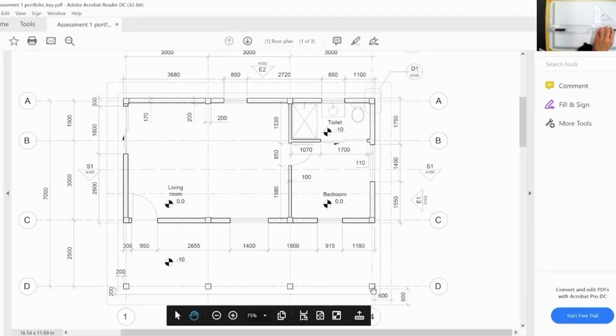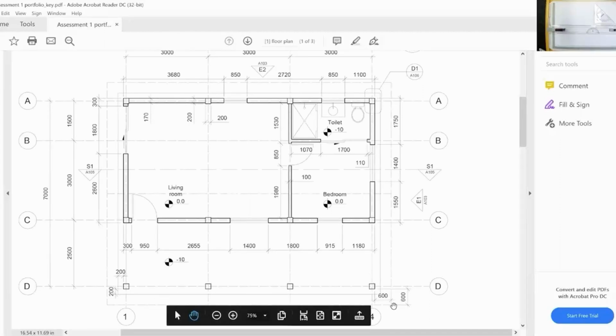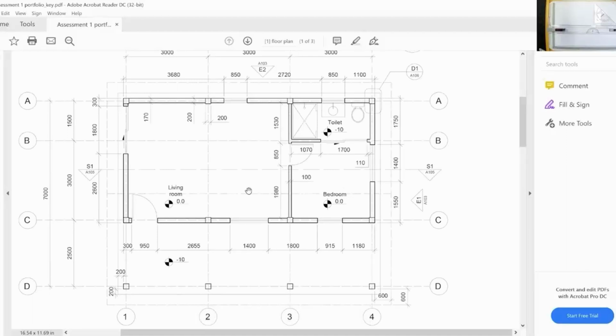So what am I going to see if I'm standing here looking straight at this facade? I'm going to see this column, a void here, right? There's a void here because this is, again, the porch area. There are no walls here. We'll see a segment of wall, a window, and another segment of wall. All of these covered by a two-slope roof, because here I have the information that gives me the midline of this roof. So I know it's two slopes, a two-slope roof that covers all this